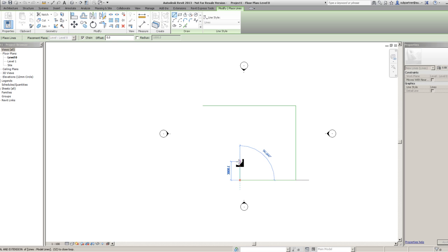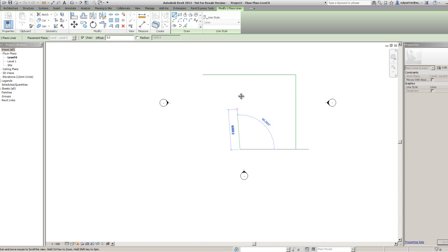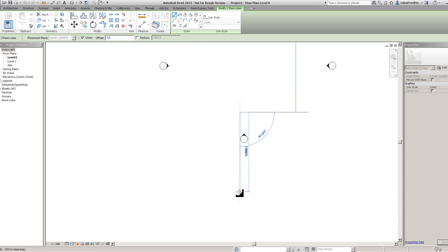Well, instead of getting my calculator out and trying to convert things, what you can do in this, if I've got to draw a line, let me just pan down here, at 15 foot. What I can do, if I just bring my mouse down to the direction I'm going to go, I can write 15.